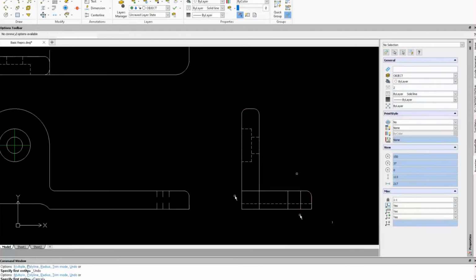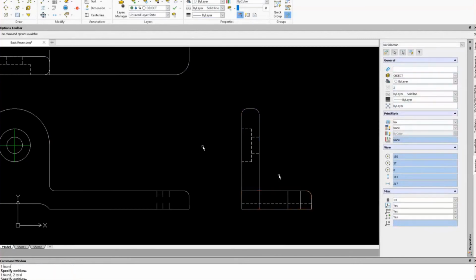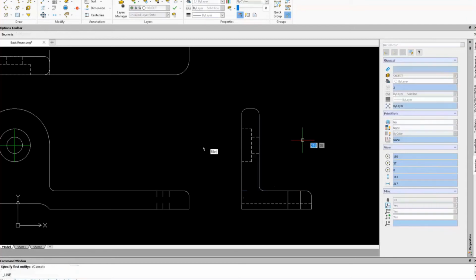So when you've got these rectangles fully defined here, it makes it difficult to do these fillets. So what I'm going to do is go ahead and explode these rectangles. That way, when I do the fillet again, I don't lose so much material when it does the trimming. So all I have to do is add back in a line here.